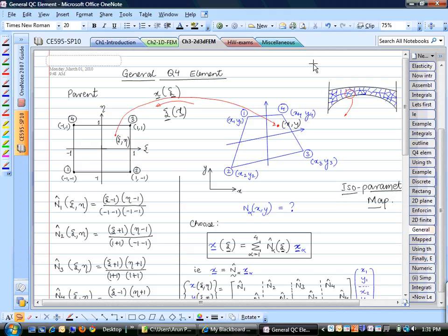So take a look at the solution for the truss code that I posted. For the two-dimensional truss, again, you will have 2 degrees of freedom at each node, right? So almost the exact same lines of code that I had there. See how the element degrees of freedom are being constructed for the truss problem. So using the same thing, you can construct your element degrees of freedom vector in MATLAB for the three-noded triangle. Okay. Any other questions?